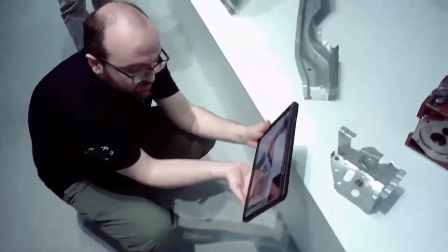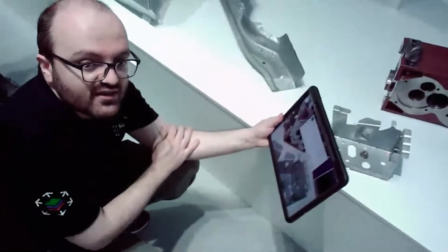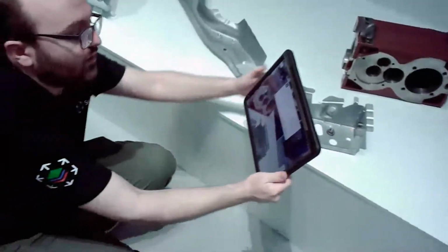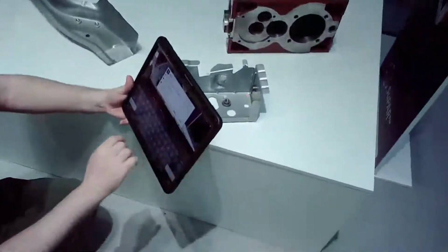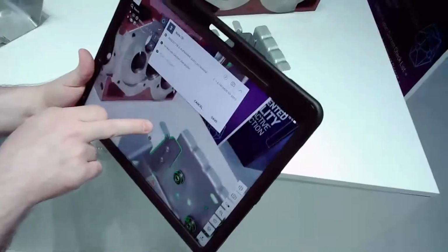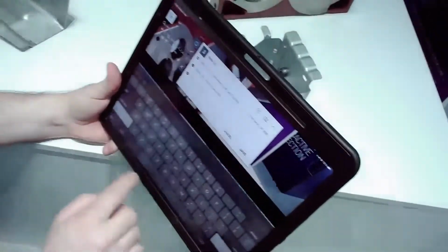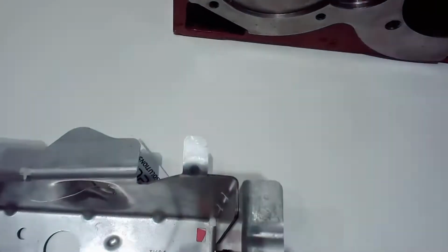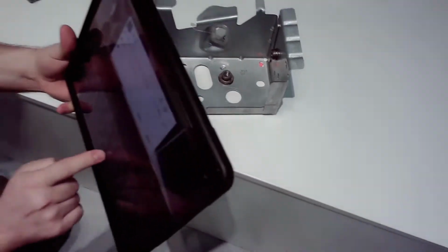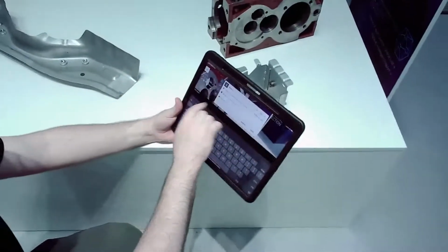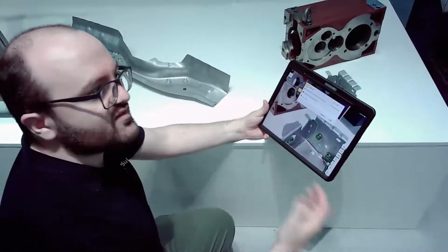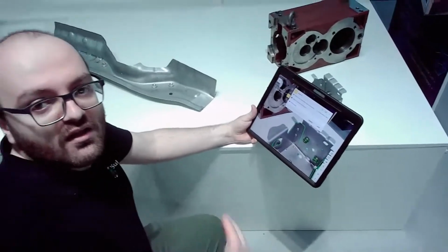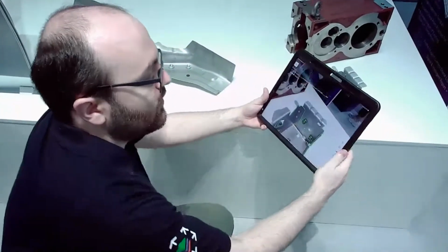The problem I see here is that there is a little bend in this point. So I'm showing this to the camera, and we can see that this part is bent. So I'm writing the part is bent, and I'm saying partially okay, because it could be inside the tolerance, but we need to check with the caliper, and we need to check with the measuring system.